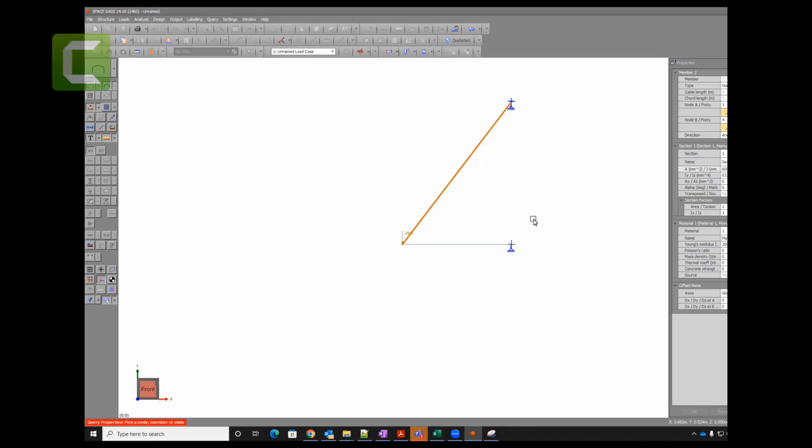If you want to see, you can click on these and you will be able to see the member sizes. Otherwise, we just keep it on the wireframe. You don't need to do the second one. Otherwise, if you have different cross sections, you can do a second one. But once you've done the first one, it will have all the properties. We don't touch the I and A and alpha and everything. We just need this Young modulus and this area. All right, so far so good. Anything else? I think we don't need anything.